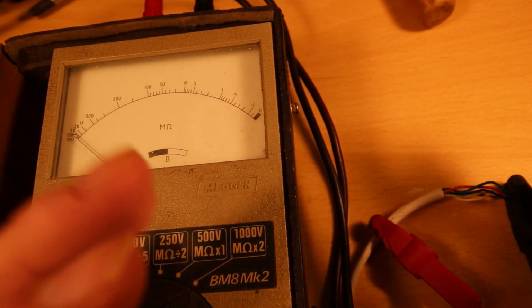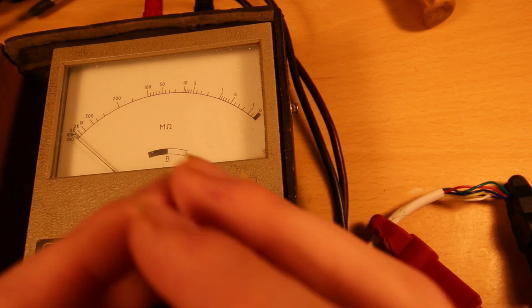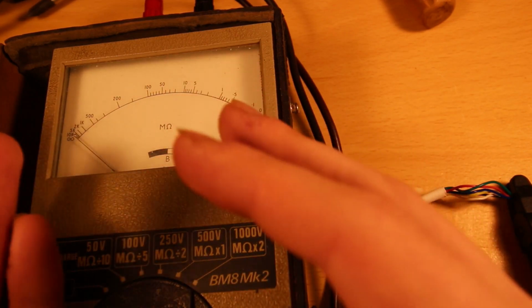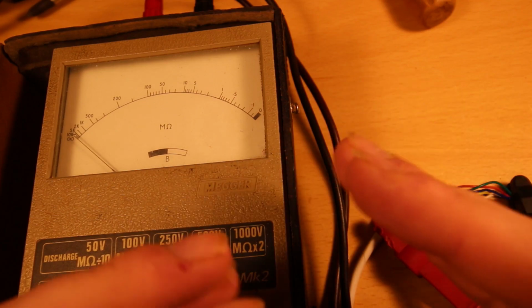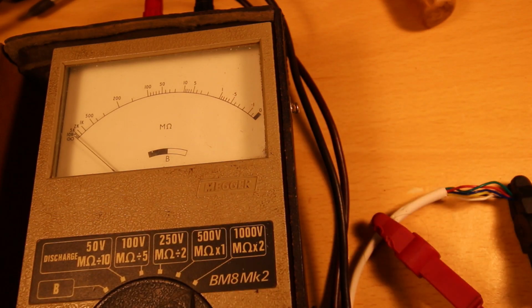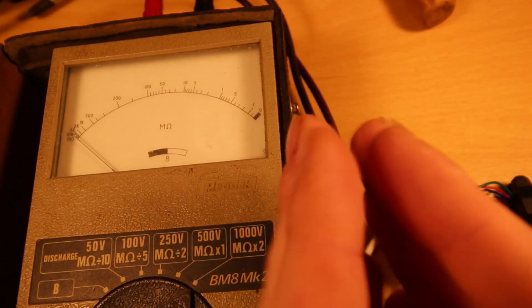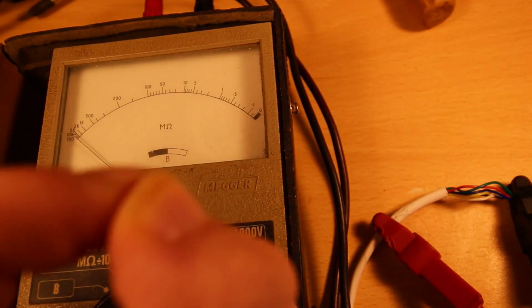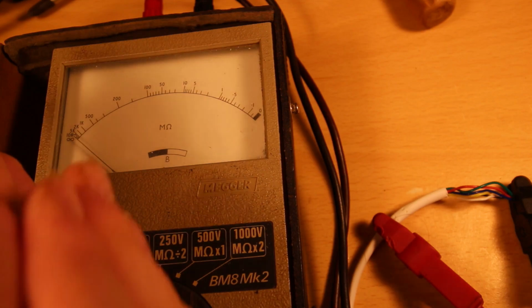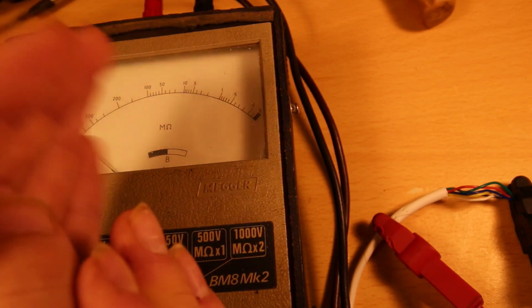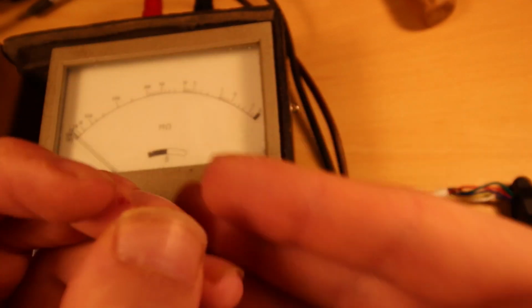That's an enormous amount. So when you compare that resistance of 20,000 million ohms to the resistance of the cable, which is like half an ohm, the enormous majority of that current will flow through the cable, but a tiny part of it will flow through that resistance between the insulation, between the cores. Some of it will, but the vast majority of it will take the lower resistance paths.